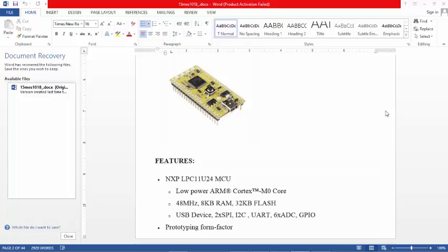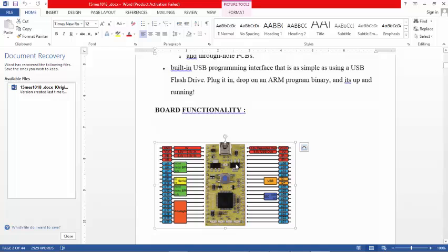How to interface different analog sensors with our embed board. So here we choose the platform, that is embed. It is a product of NXP, LPC11U24, and I will use the analog pins of this board. Actually the analog pins are P15 to P20. So I'll use the last 3 pins, P18, 19 and 20, and we will see how to write a program and how to dump the program inside our board.